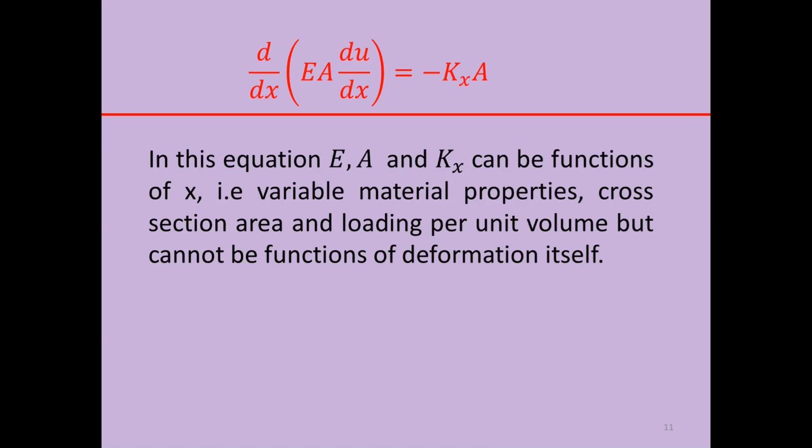But the thing is that these values cannot be a function of the deformation itself, because this is going to make these particular equations nonlinear, and this is one thing which we are going to deal in the future classes. But for the time being, it is just assumed that elasticity, cross-section area, and Kx can be function of space only.